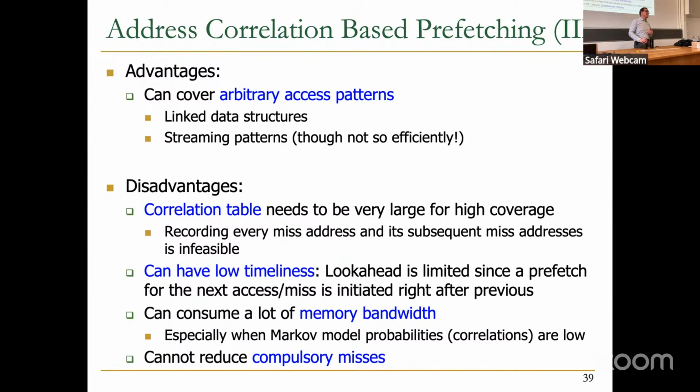It could be dynamic, yeah. A lot of the design choices can be dynamic. Thresholds can change, and thresholds can be adaptive. For example, a lot of the prefetchers adapt to the memory bandwidth availability. If there is not enough memory bandwidth, they basically throttle to lower. We're going to see throttling. But yeah, a lot of the decisions are dynamic, but some of the thresholds may not be dynamic.